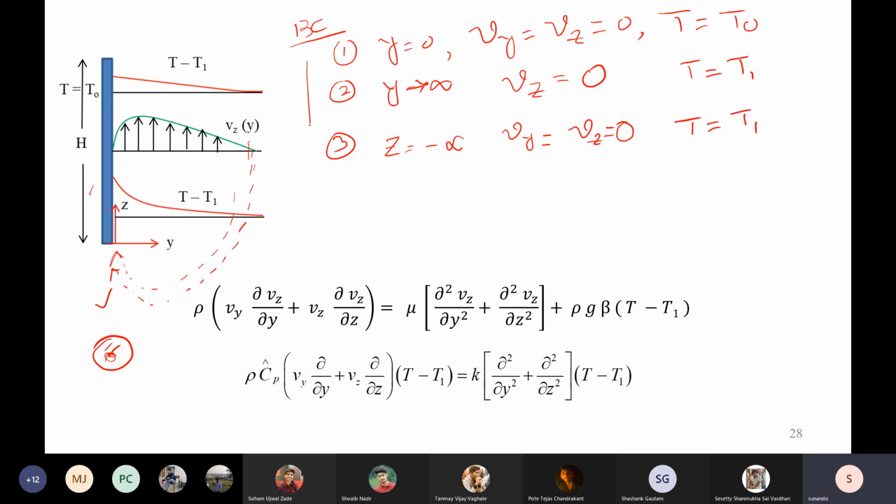So with these three boundary conditions and these two governing equations, one would attempt to solve for the temperature profile and try to obtain, as we engineers try to do, some relation for the convective heat transfer coefficient for the natural convection case. More importantly, the way we handle these cases is we would like to find the Nusselt number correlation for such a situation where there is no imposed pressure-gradient-driven flow. Now, to solve this is kind of problematic.